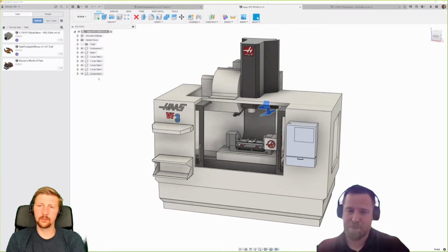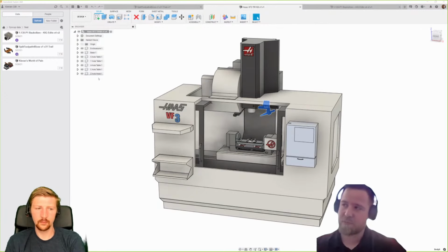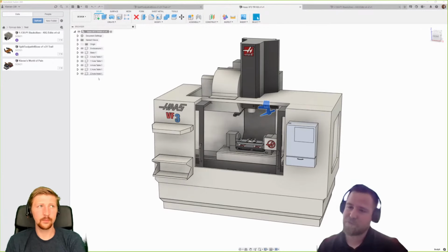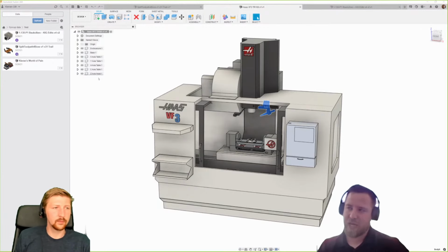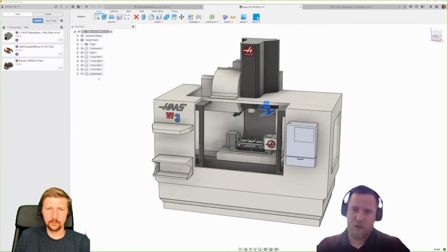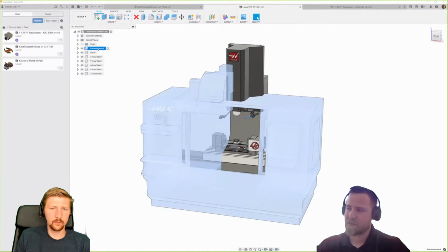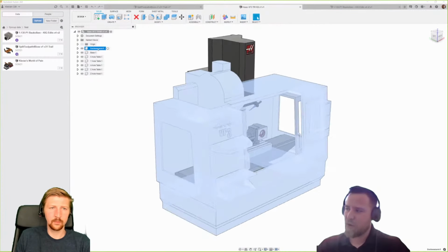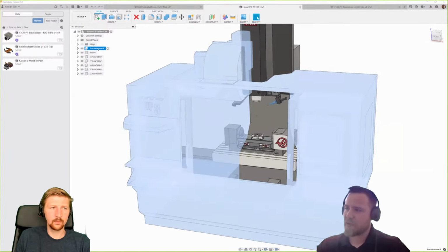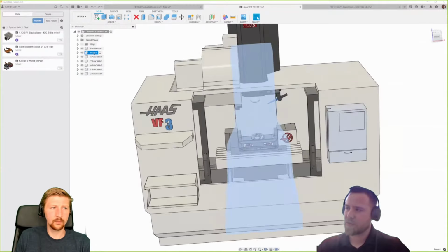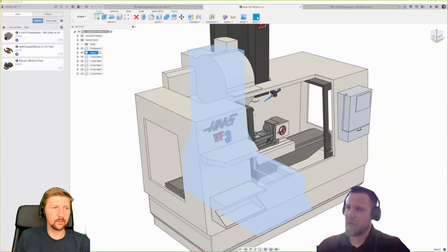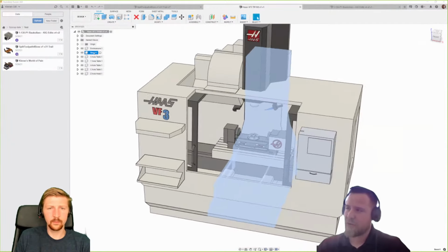This is the most time consuming part of Machine Builder, bundling everything up in the main orthogonal axes. My recommendation is to bundle everything up in A, C, B, X, Y, and Z, depending on the axes you've got. And also you want to take all of the components which are not movable and bundle them up in the base or the enclosure. So that's my recommendation for now.